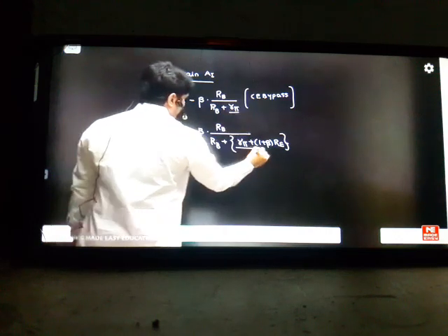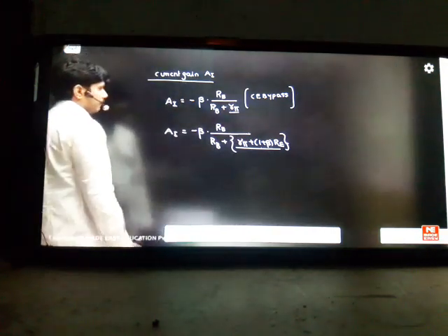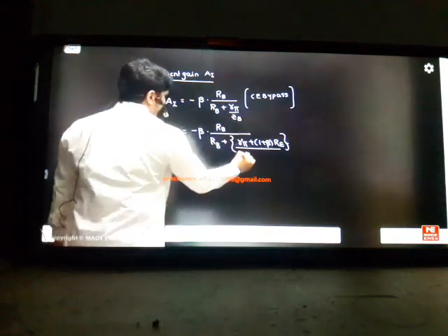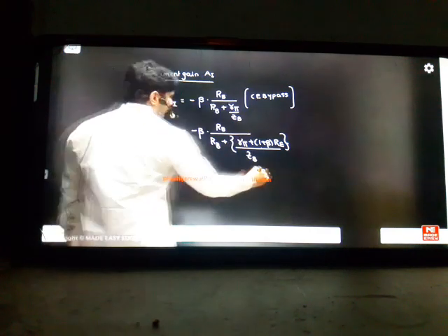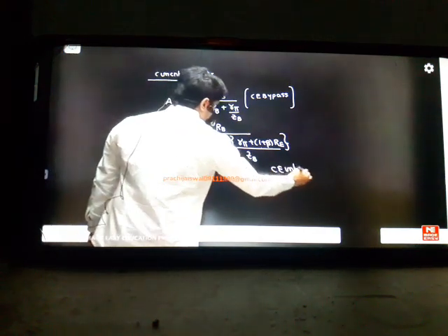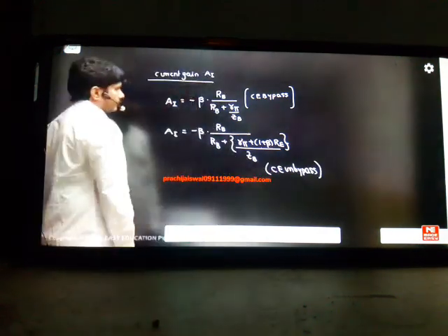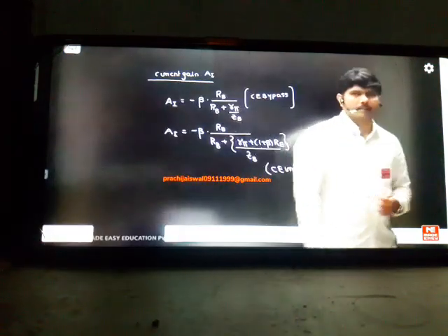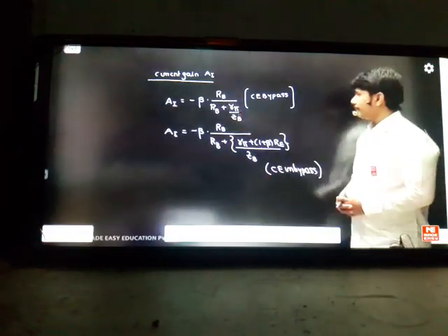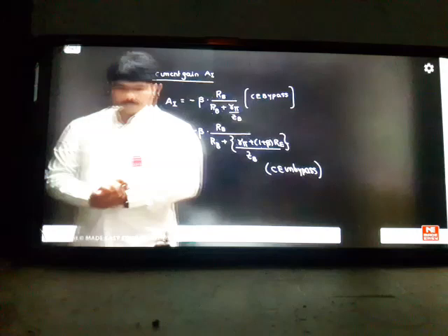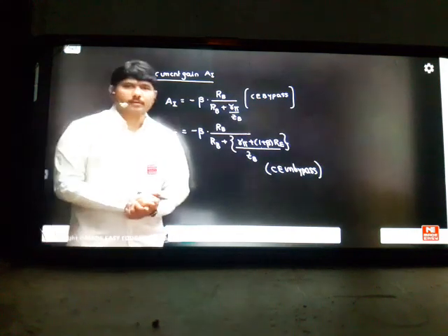So this is the difference between these two formulas. Here R pi is the input impedance. Here R pi plus 1 plus beta times of RE is the input impedance. This we call ZB, we can say. Impedance at the base will change. So this is the concept of common emitter with and without bypass. So why not use a trick like this without doing the total derivation? Current gain I will not give much importance in my class because it's a small shortcut trick for us. Straightforward you can answer it. So with this, I have nicely completed the total section in the class.